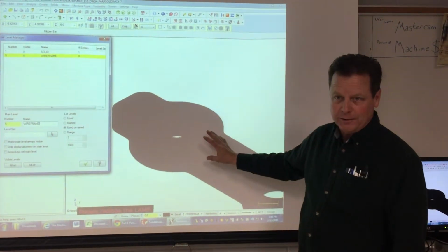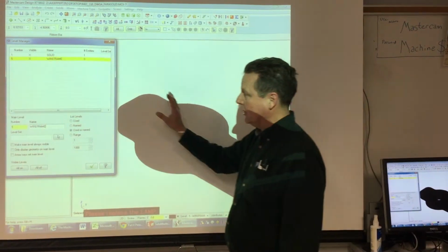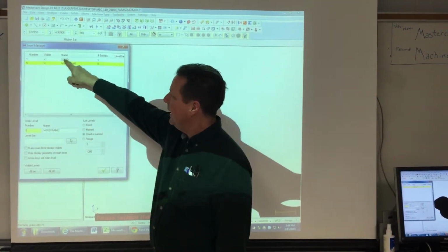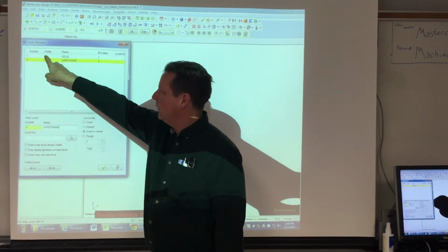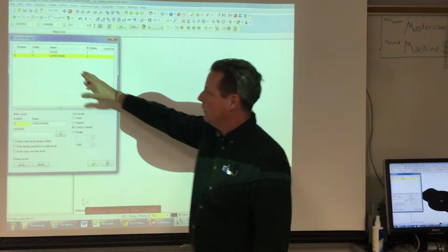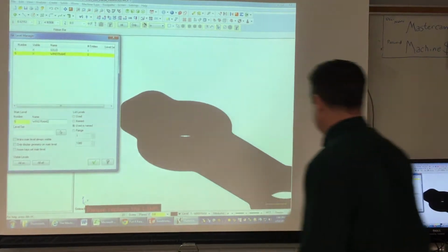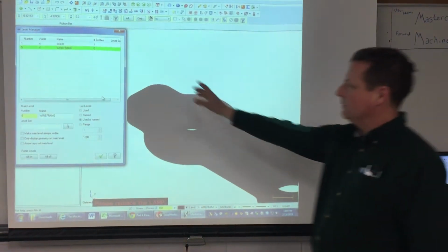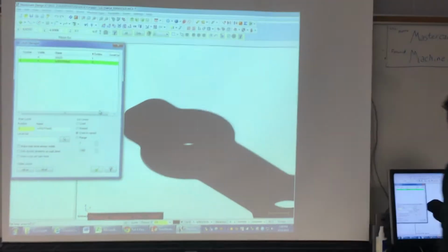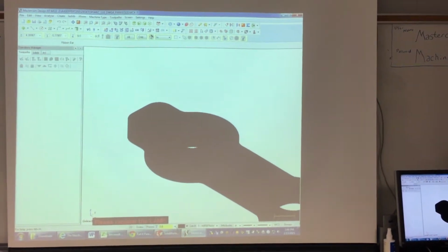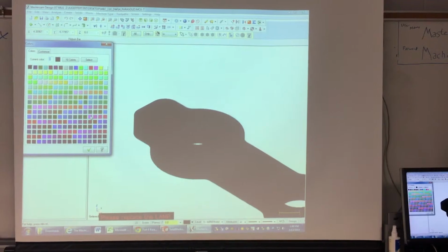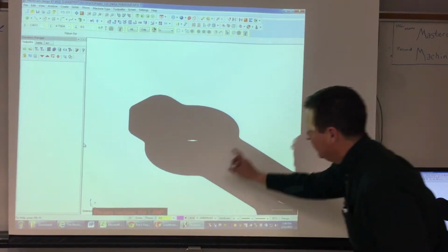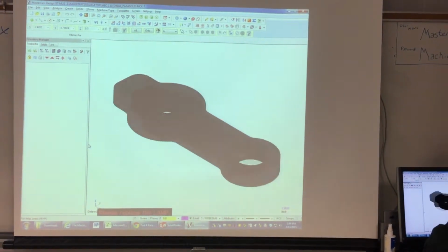That will be the wireframe that I need to click on my geometry for my toolpaths. And then I'll have them separated here too, so I don't have to see this big black solid anymore. I'll only have my wireframe. So I make sure that wireframe is the active level by making it green, and then I green check. Then I'm going to change to another color so that it comes up like purple 172 for my edges.